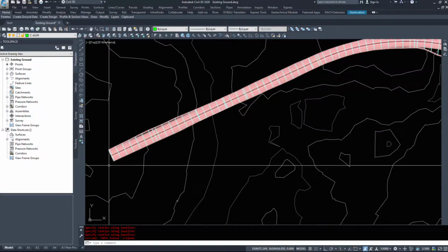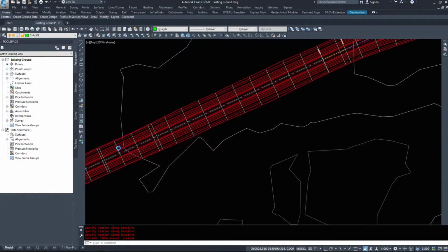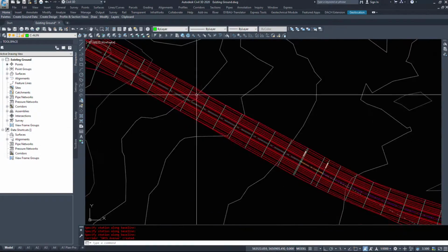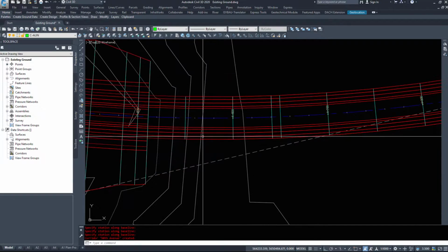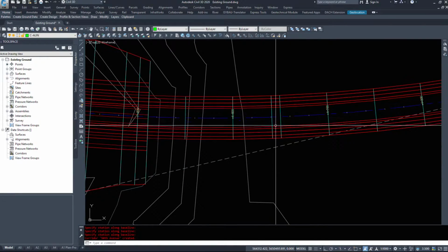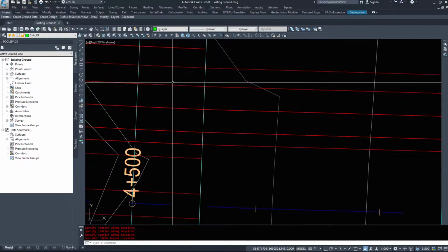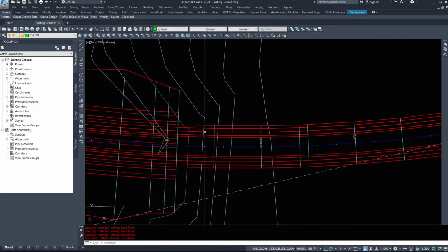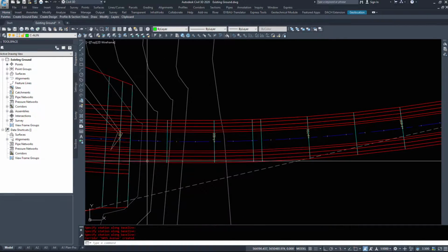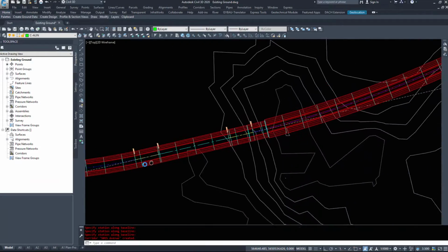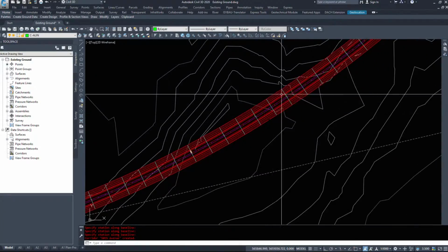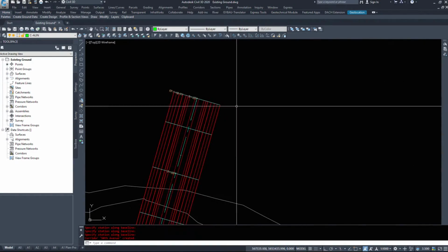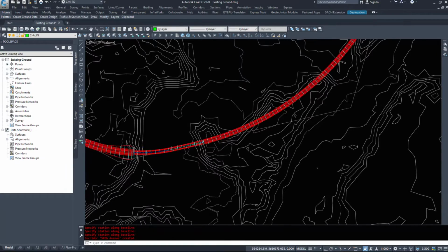So we have our corridor model now, and as you can see on the left side, we have our corridor here. We have our daylight targeting out, coming down, and then we have a transition to our bridge. So the corridor actually gets skinnier. However, our shoulder continues, our driving lane continues, our driving lane continues, and our shoulder continues. So we'll know if we did it vertically correct after we go and build a surface out of this. Then we cross the gap and we come back to a corridor piece without any targets, and we can tell that because it's the same width the entire direction.